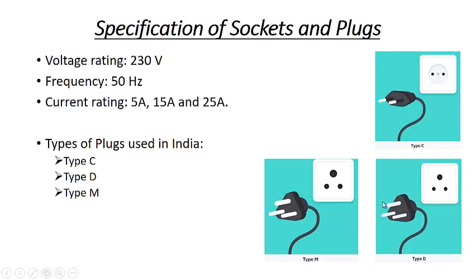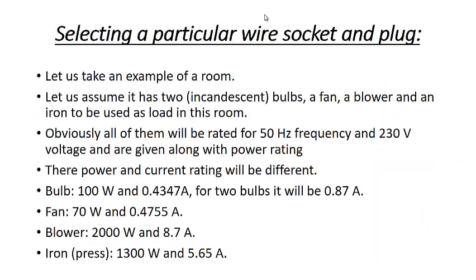So these are the different types of the plugs and sockets with different types of rating that we usually use at our homes. So you need to remember this, because when we calculate the load of your room or sometimes house or sometimes at the balcony, looking at the load, you will calculate the current, and as per that current, you can select which type of socket or plug you have to use for that appliance. And we will try to do the same thing.